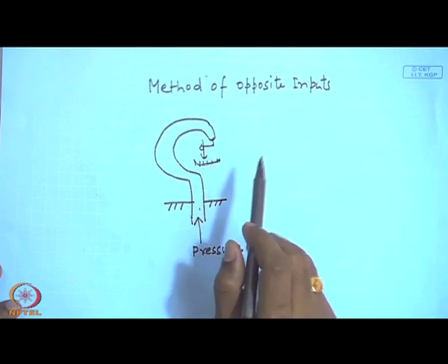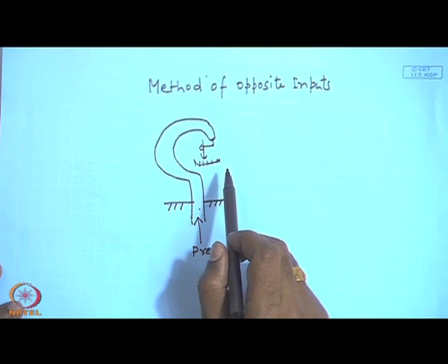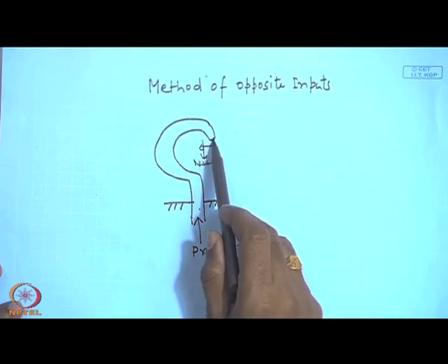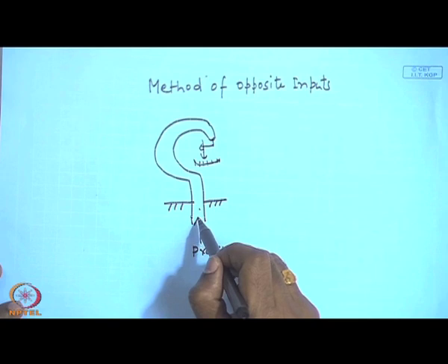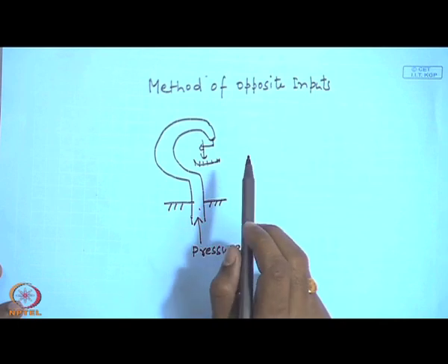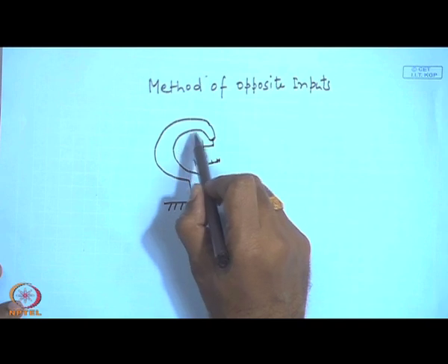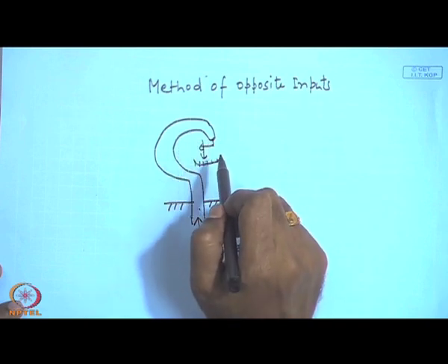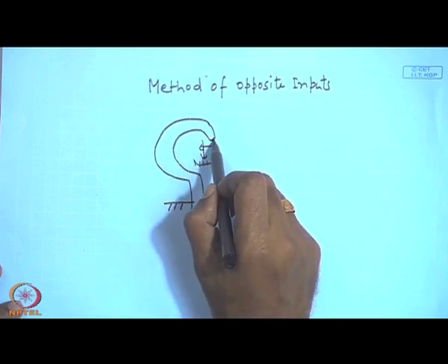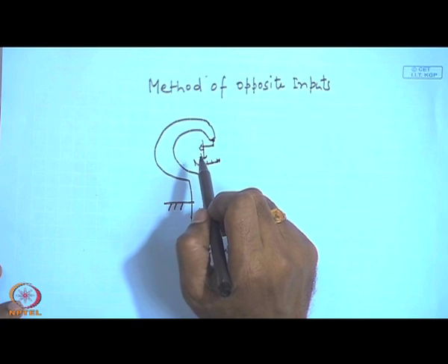But for a given Bourdon tube, other things being unchanged, this tip deflection can be considered as a function of pressure alone. Among the various factors on which the tip deflection will depend, the elasticity of the material is one.